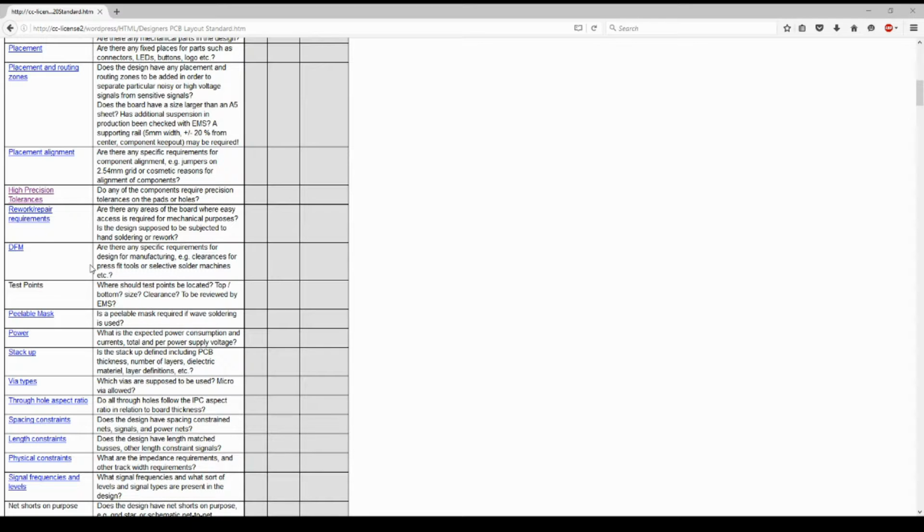If there are places around the board where we have specific height tolerances, it's also important to identify these requirements so that you can add this into your specification. It's important because if you don't, the PCB manufacturer may not know, or the EMS may not know. It can be both the placement of the component but also the placement of the pads and holes.